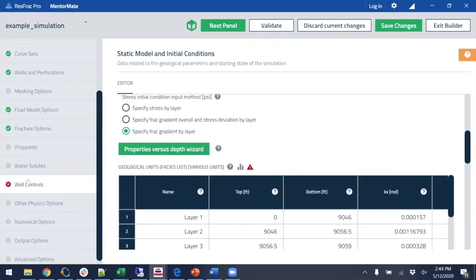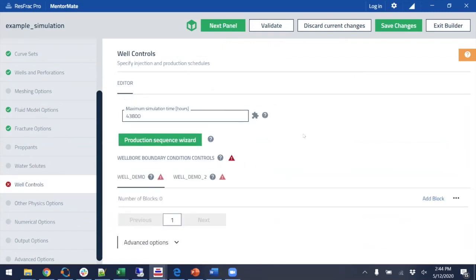I'll make a comment that I noticed today or yesterday. Again, I'll reiterate the point that if you change the boundary conditions all the time, then it slows down the simulation way down. So personally, when I'm doing this, I'll change it maybe once a month. If I eyeball the bottom hole pressure the first time and it looks like it was about constant for 3 years, I'll just use one bottom hole pressure for 3 years. Don't feel like you need to change things every day or every week. You're just putting in a lot of detail that's not really going to have a big impact.